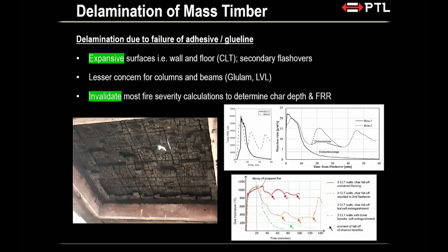So if you have failure of your glue line, you have the delamination, that sort of issue, then you need to design it properly. It's not like you can't use those products. You can still use them, but you need to find a way to design properly. Perhaps making sure that your char depth doesn't get to that glue line, that sort of thing.